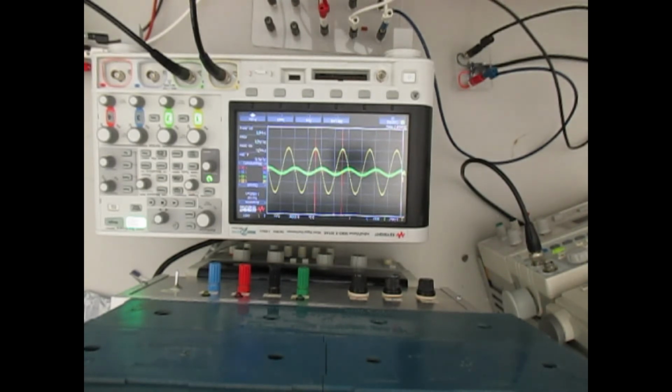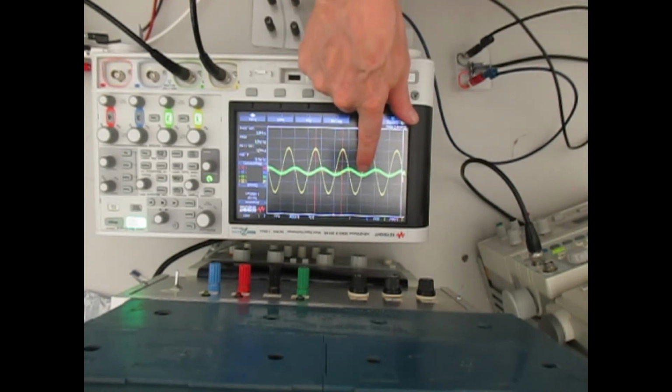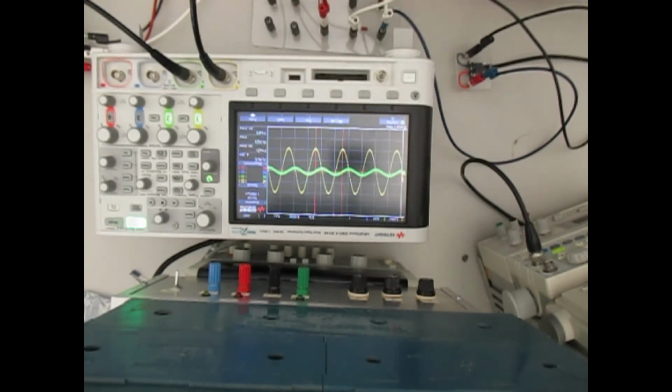And right now I'm at 100 hertz, where it's a low frequency, so the capacitor is very dominant in the circuit, right? So very little is being dropped across the resistor. And this green line here is your VR. So like we were showing on the board with the impedance triangles, right? VR and R are very small. And it's also 90 degrees phase shifted. So if you look at the peak there, it's right at the zero cross.